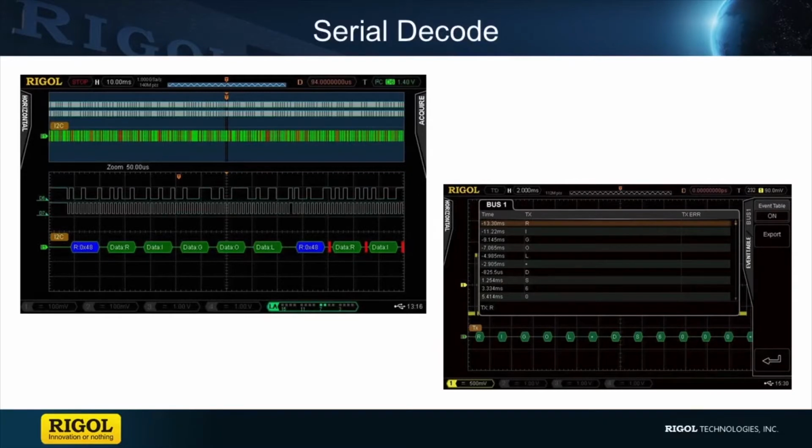So there are a couple techniques we just used to measure decoding of your serial data on your SPI bus. One of the tools we use to do that is the serial decode option on RIGOL oscilloscopes. Our 4000 series has a number of serial decode options, but the 1000Z and 2000 series instruments decode serial data as well. Today there's a bundle pack for the 2000 and 4000 series that allows you to get all the decoding options at one low price.